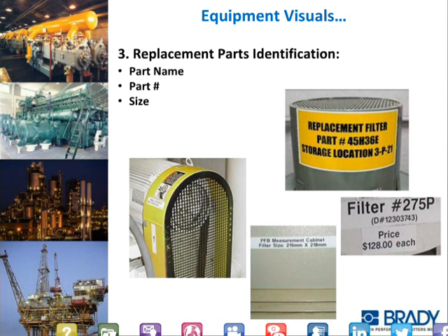Again, the advantage here with this visual is you can see through the guard and inspect it with a strobe tachometer while it's running. You can literally inspect the underside, top side of the belts, the sheaves, the keyways, and the bolts holding it all together while it's running. So you can go from a downtime PM to a running PM with that type of modification.